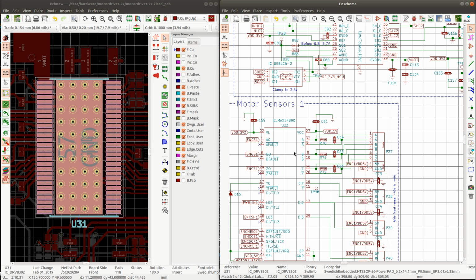It would be a very clean approach to implement this as a separate driver. But we are still going to have to have some form of quick notification to the motor driver about any errors that occur on these lines. Because we want to read the errors and they have to be read over SPI, this is not going to be happening in real time, but it still needs to happen, and then the notification still needs to get to the driver that is responsible for a specific type of motor that we're running.